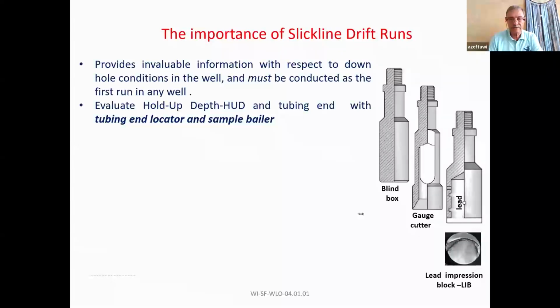Last question I have. Does a low pressure system like coal bed methane production require the same BOP system setup as a high pressure system? First, let us agree with each other: what do you mean by low pressure and what do you mean by high pressure? There is nothing called low pressure or high pressure. There is no line between the low and the high, but we have categories. The API puts it in category 0, category 1, category 2, category 3, and so on.